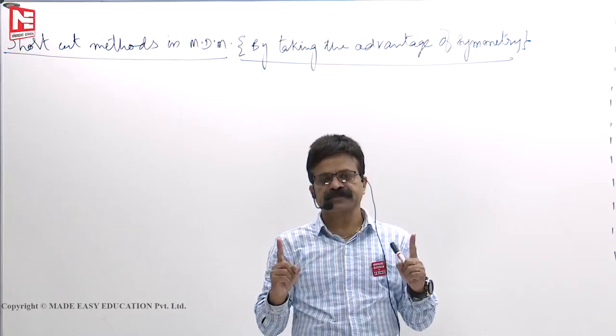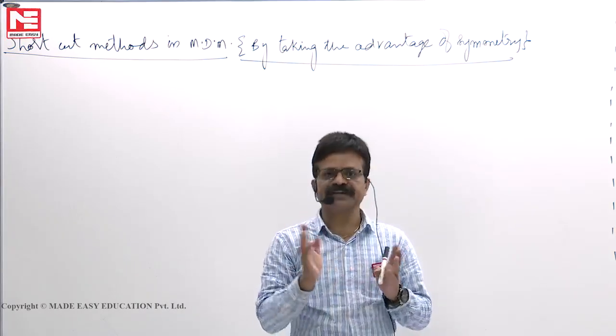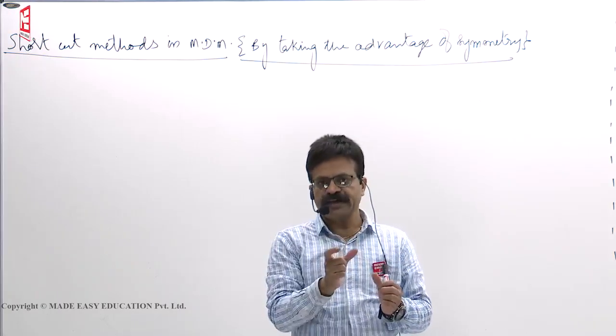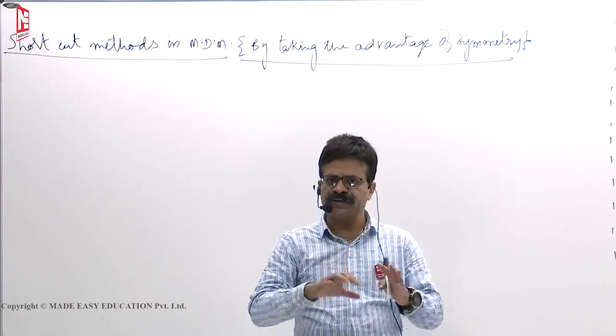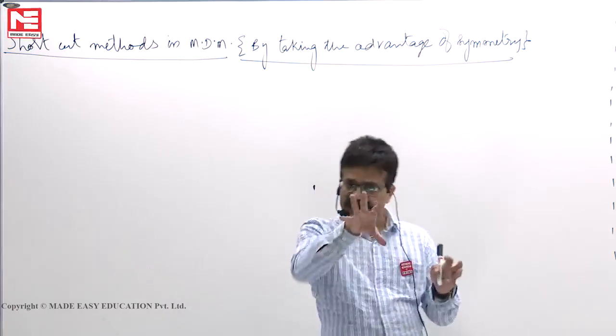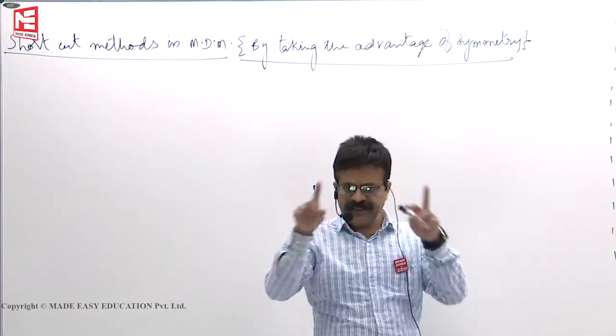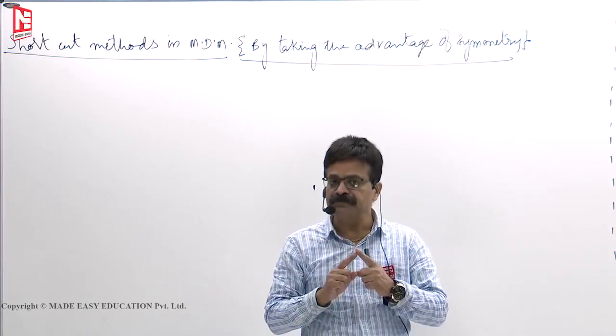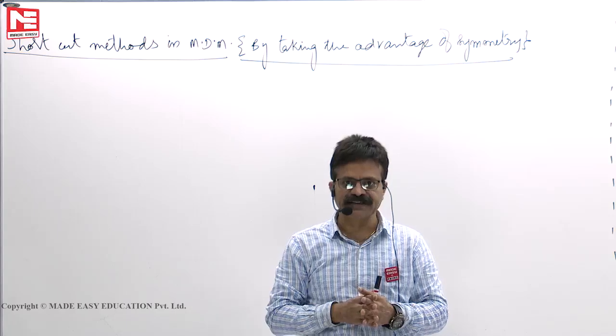If a simply supported beam is symmetrically loaded, say, your shear force, your bending moment diagram, deflection profiles, everything are symmetrical, reactions are symmetrical. So from that, in the trusses, what we have done: if the truss is symmetrical and loading is symmetrical, then member forces also will be symmetrical.